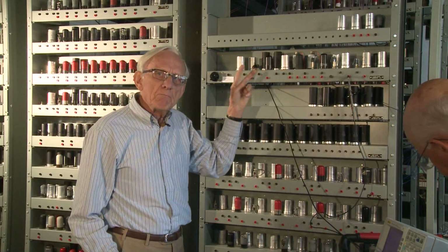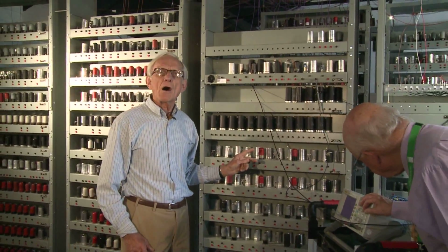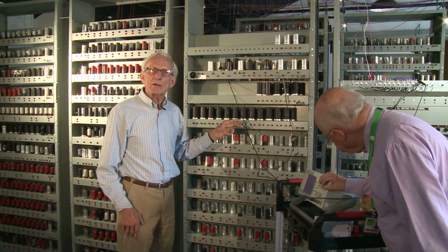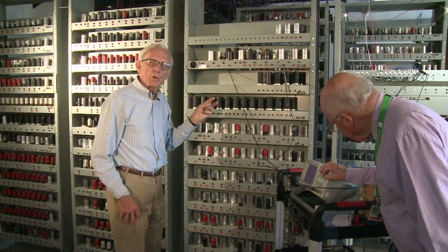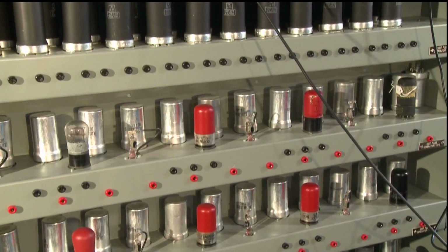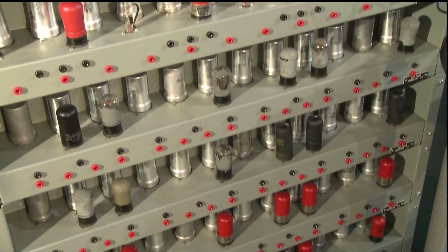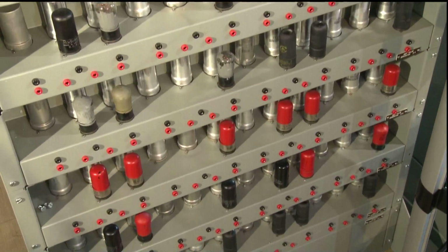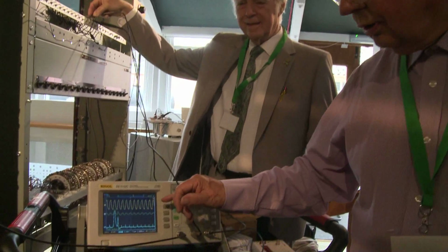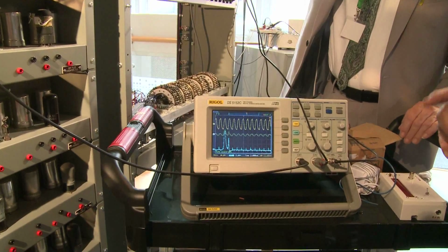In addition to that, an important part is to have some pulses which tell us where we are within a word, or whatever unit we use. In our case, 36-bit words. We need pulses which tell us where we are within the word. And these chassis here divide the clock pulses by 36 to give us one pulse for each digit position in a word. The yellow trace is the clock pulse generated here, distributed over the whole machine to keep everything in time.